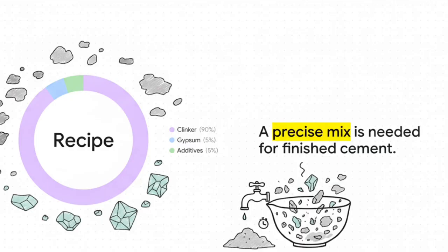Now, clinker alone isn't finished cement. It requires a highly specific mixture. Taking clinker as the base, the plant adds about 3 to 5% gypsum. This is actually to strictly control the setting time for when water is eventually added on a job site. And depending on the exact cement type, specific additives like fly ash, slag, or extra limestone are introduced here too. It's like a giant, very precise recipe.